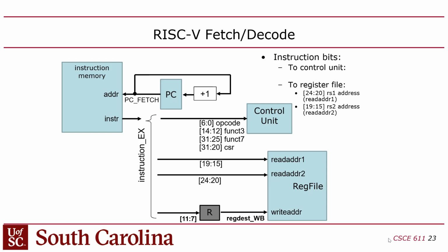So this is obviously different from MIPS, because remember, RISC-V and MIPS have vastly different instruction encoding. I used to have the MIPS one memorized, but I don't have this memorized. This one is way more confusing than MIPS. So you may have to refer back to this, because the encoding is wackadoo. The opcode, for instance, used to be the first 6 bits in MIPS. Now it's 7 bits, and it's the last 7 bits, the rightmost 7 bits. That's the opcode. And then they have Func3, Func7, and CSR.